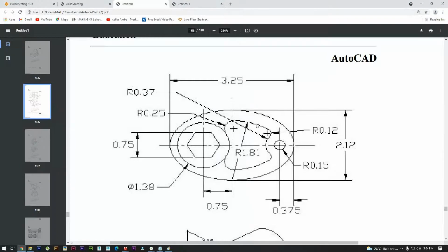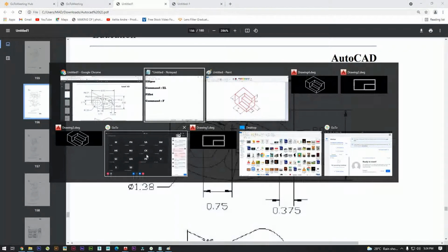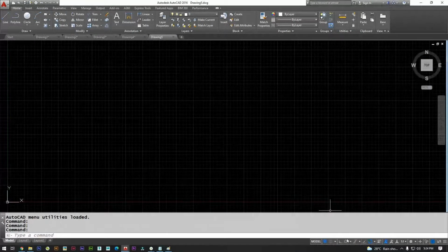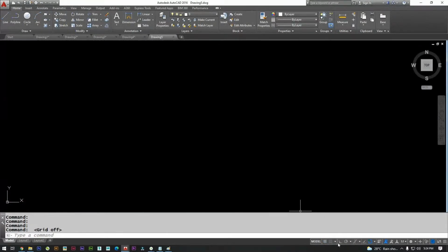First we need a line, so 3.25 and 2.12. So let's take a new drawing. Great. Now turn on the ortho. Whenever you're drawing straight lines from today onwards, you can turn on the ortho. L enter, click, no need of at the rate or any angle, 3.25.